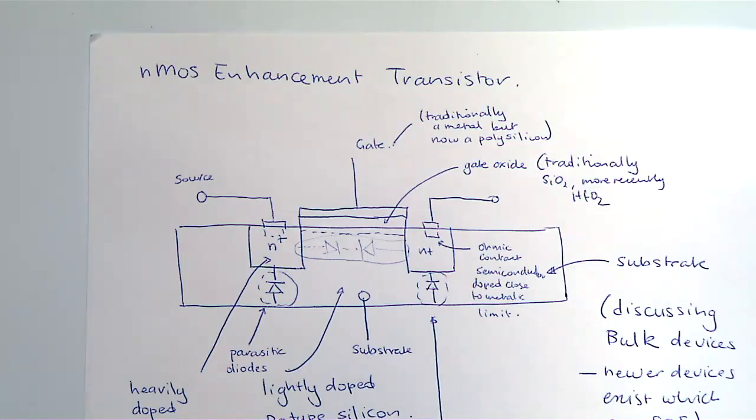But essentially what happens is you have a large wafer, right? Usually these wafers are created in large crystals, which are these huge things where you've got molten silicon, and you put a little bit of a crystal in there which acts as a seed. Then you start pulling that seed, which begins to form the crystal out of that molten piece of silicon, and as it cools, it begins to form this large cylinder.